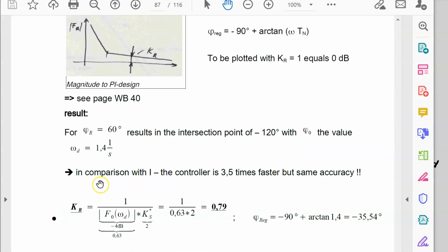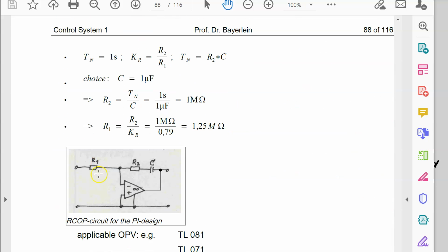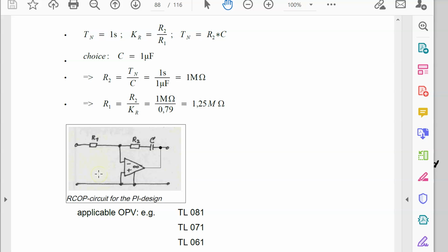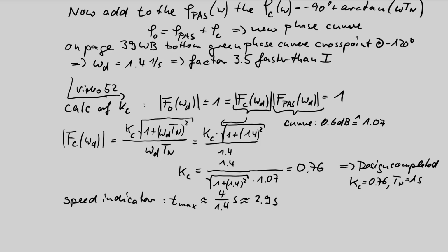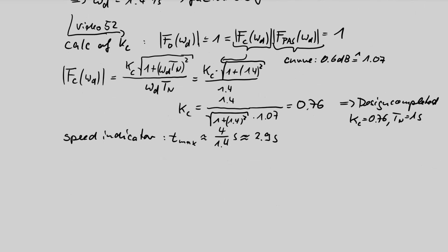Yes, in the student paper, you can see we have added a realization I should do on my paper. How can we realize this controller with an operational amplifier circuit? This is very simple with the following calculation values. Note that we have discussed this circuit of a PI controller in chapter 3.